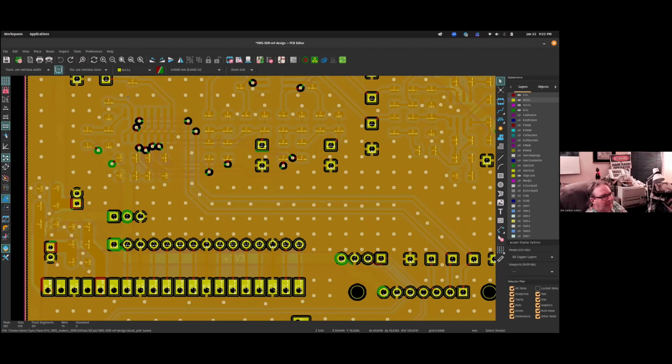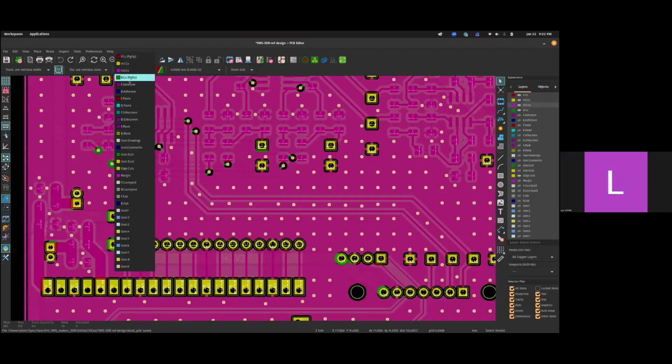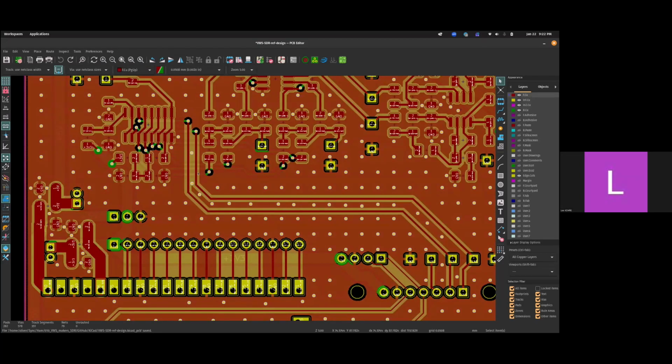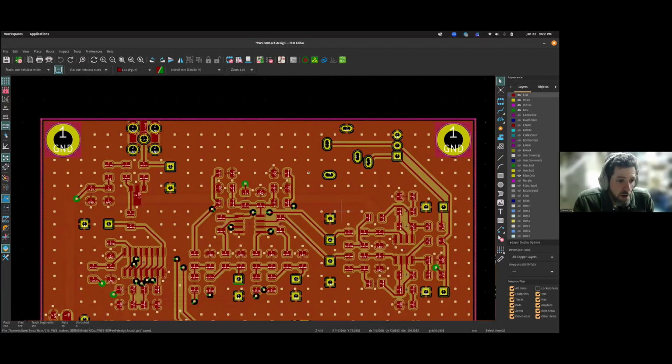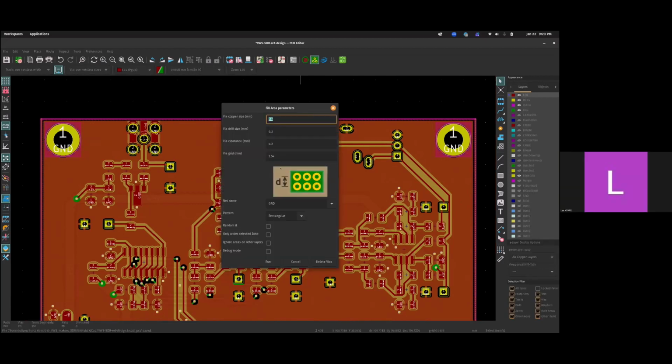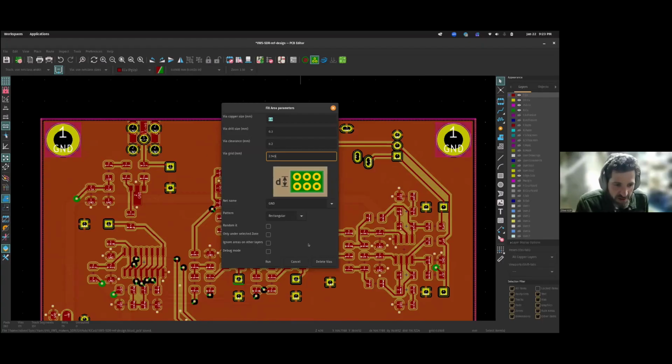Okay, cool. And I think one other quick one. When you added your component, is there a way that it'll redo the vias to avoid what you added? Yes. You can click on any of these vias, and it will select them all as one group. They are grouped together automatically by the tool. So I can delete them, and all the vias are gone, and then just redo them. Okay. And then redo it at 5 millimeter spacing. Okay.